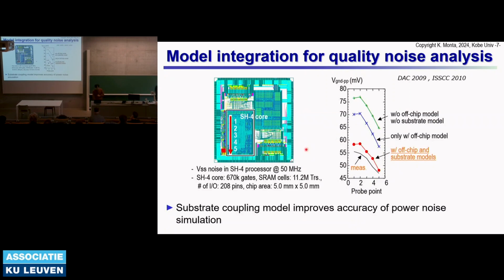We had some ways of assessing the simulation techniques with measurement techniques. In this case, we have an on-chip monitor that can give you an idea of what kind of voltage variation is happening on your power domain, the power delivery network. Voltage variation is directly caused by the current flowing into the power delivery line. The power delivery line has impedance, and if current flows through the impedance, that will create voltage variations. That is measurable by the on-chip monitor, and the results are compared with the simulation techniques. We have four different plots here.